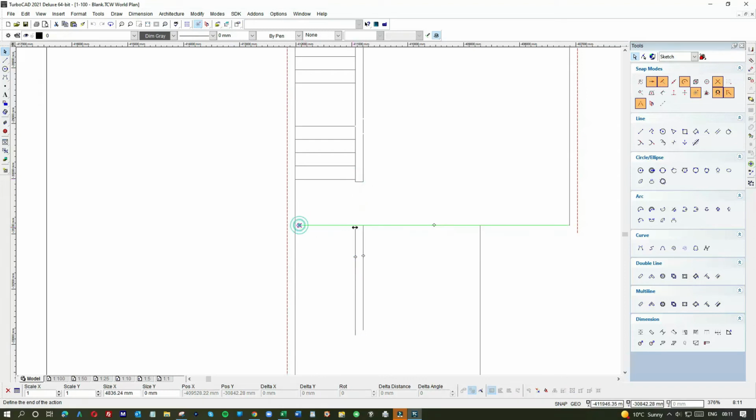So what tends to happen here is that this wall was actually the main house wall. When they built a back addition, they continued the thickness on this being a double thickness, like an external wall, even though there's a back addition on. The reason for that is it takes the weight of the main roof. So they kind of had to.